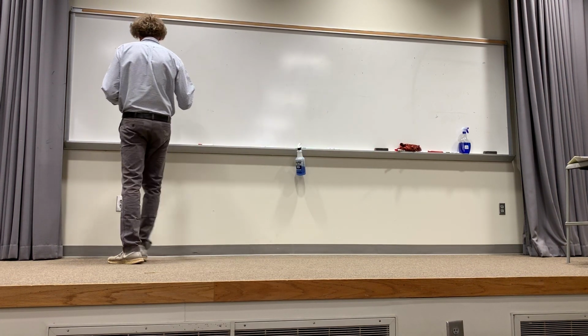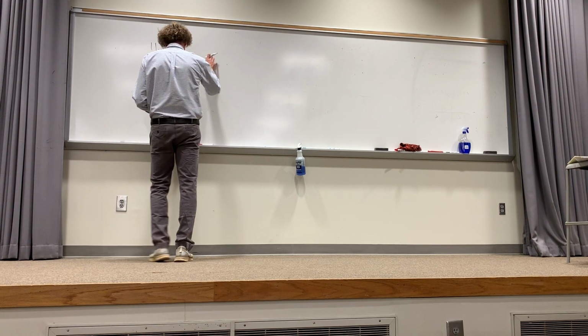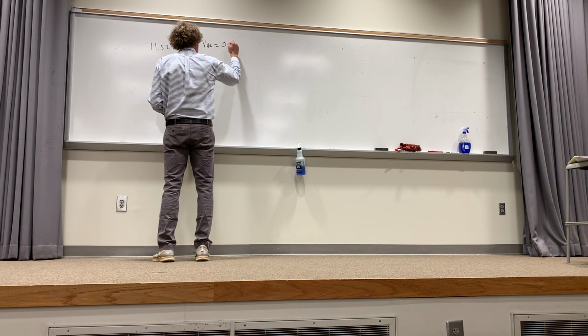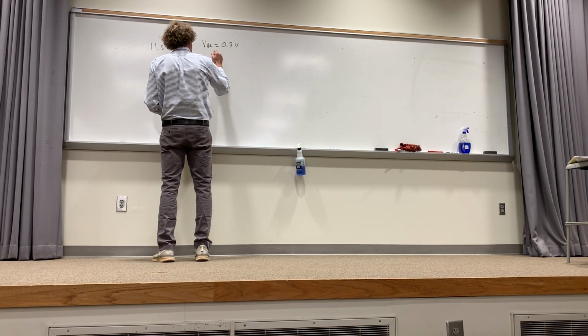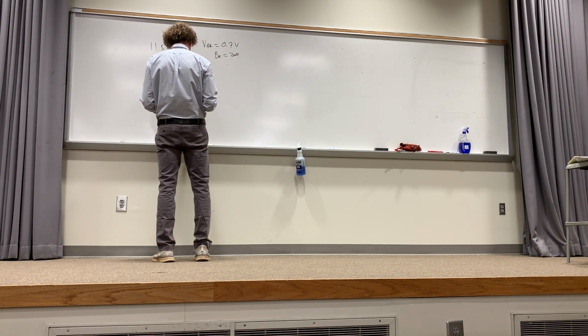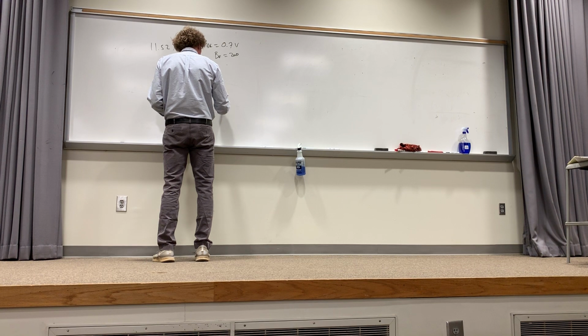For the record, this is 1152. And here, VBE, as in most cases, is 0.7 volts. That's what it should be. Beta forward is equal to 200. That's more common. And they have this. They have 9K and then 3K.